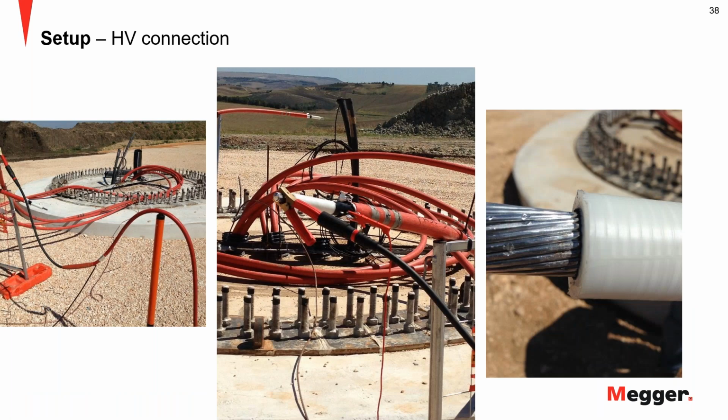Here is an example from Italy where you see, again, the cable is suspended, and sometimes it can be easy means, right? They had one of these plastic posts there, and we use this to suspend the cable. You connect it, there in the middle is your connection, and you run the proper ground connection, and you will have good measurement results.